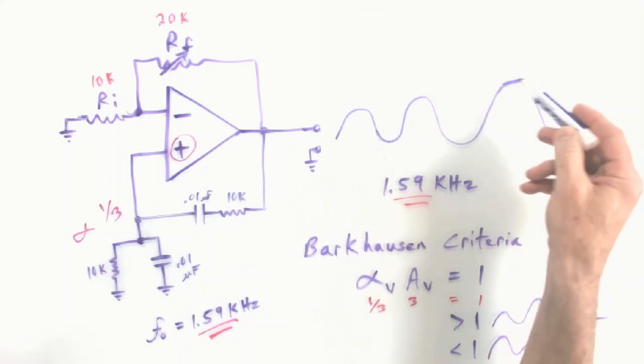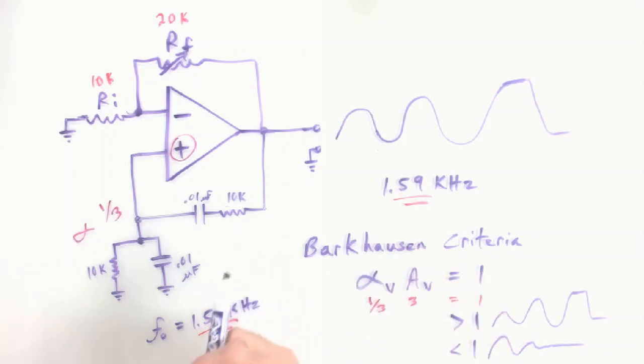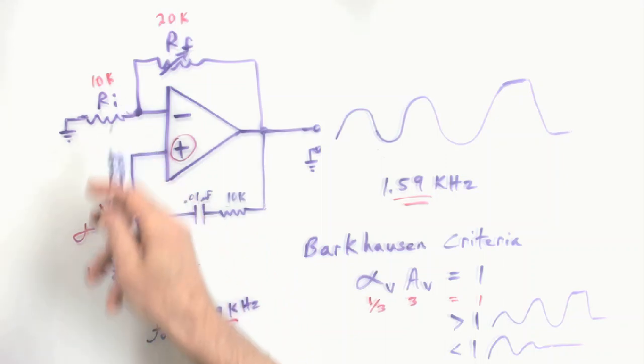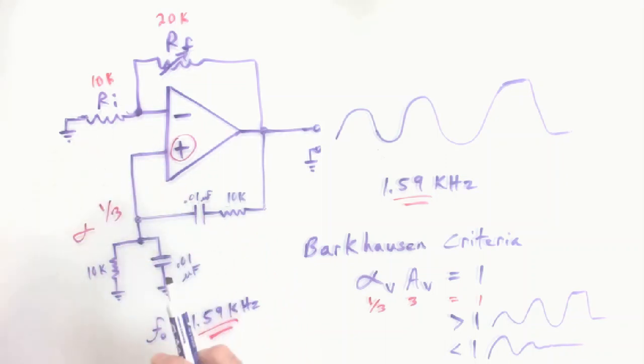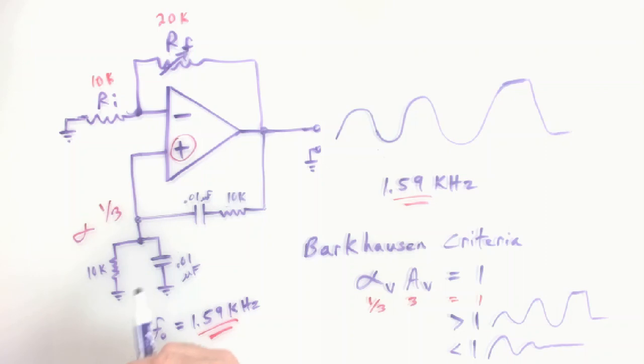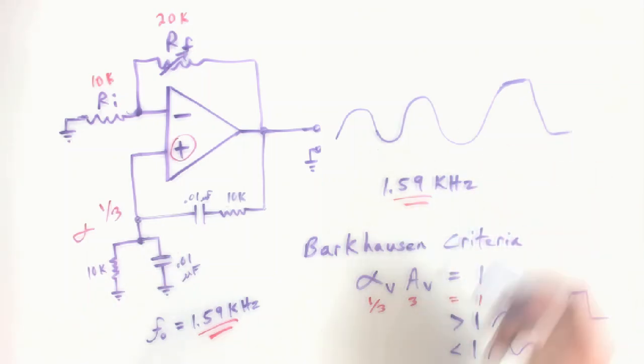It grew to a little bit of distortion, a little bit of clipping, not a lot, but at least it showed the concept. So if you don't have a potentiometer to use, you can fool around with fixed resistors, but it might get a little frustrating. You either get lucky like I did, where it did work out, but the tolerances of the resistors and so on can make it a little bit tough. But you can definitely experiment a little bit with some fixed resistors. Maybe you'll get something oscillating. Maybe not perfectly distortion free, but that'd be a start to play around with the circuit.